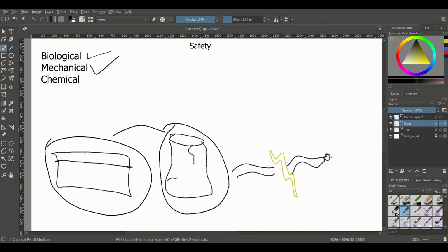Now, another mechanical hazard that we'll often run into is electrical. So while we have sharp things everywhere, sometimes those sharp things come in contact with electrical wiring. Now, I don't see a lot of scenarios where an electrical cord might come across your microtome, but who knows? Maybe somebody's moving something around, the blade guard's not up. But also a lot of places have office chairs or stools on wheels, and sometimes the cords get run over. And when that happens, we have to take a look at those electrical components and make sure there aren't any exposed wires.